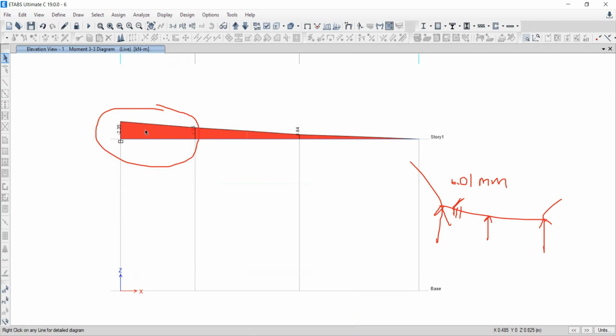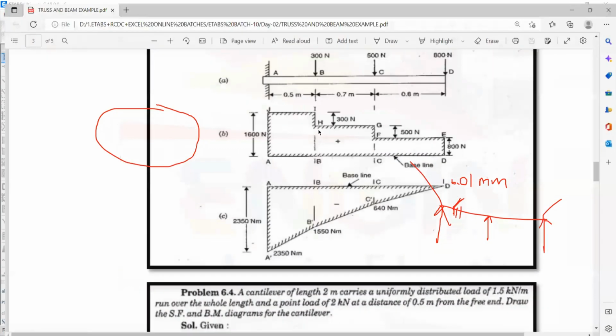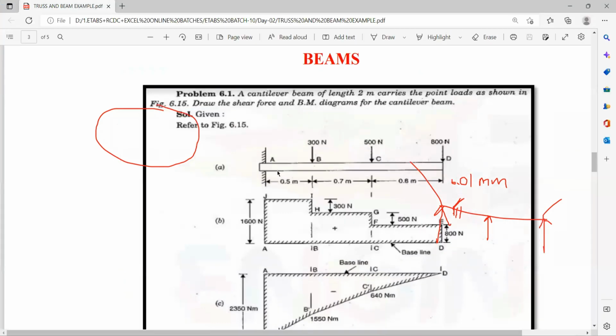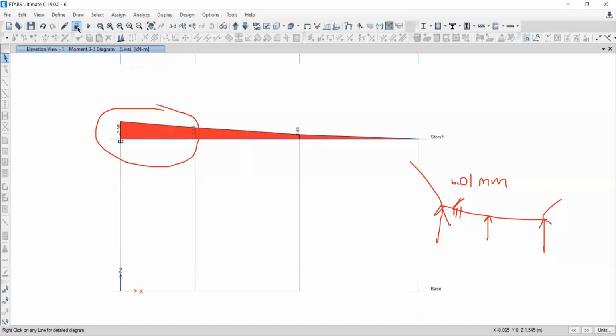The important thing is what? Actually this beam is a single element, and we have modeled all of this in 3 parts. Okay, it is no problem, but I feel it is not more correct. There is an option, we can model it as a single element, but if we do a single element, what problem will come? We will not be able to give point loading. Assigning the loading will be difficult. Okay, so that is not the case. We can do it. Go to unlock, close it.